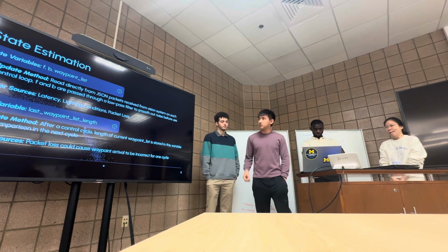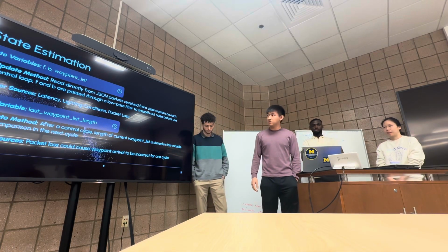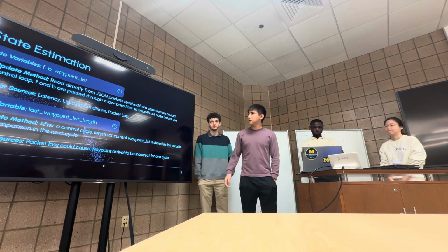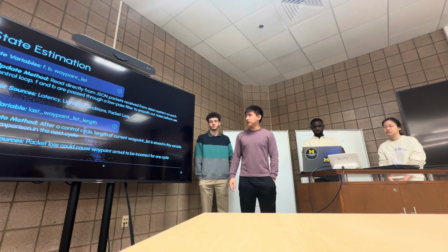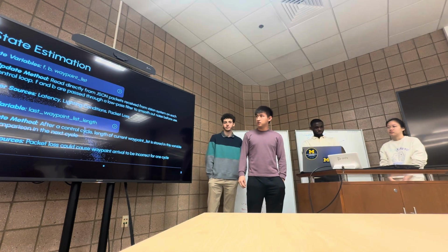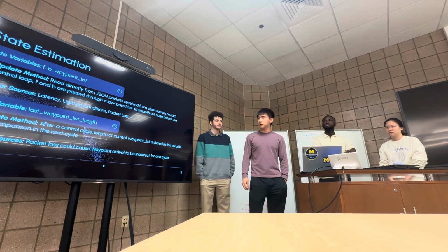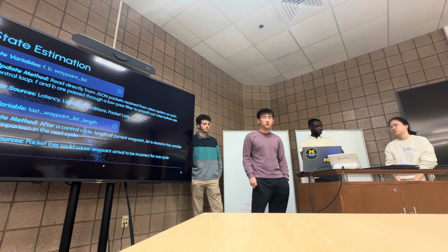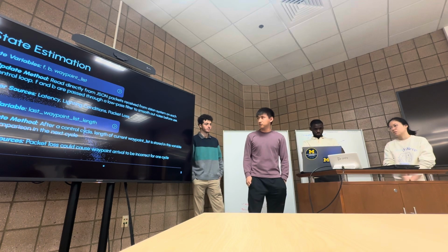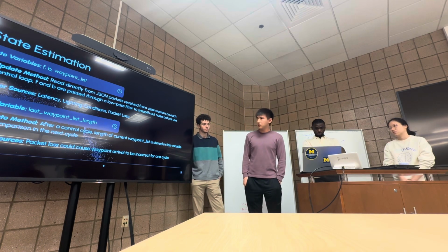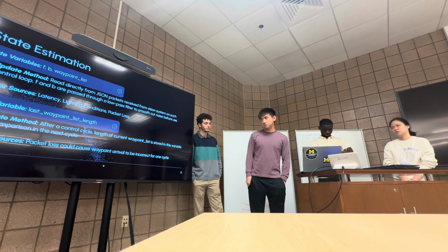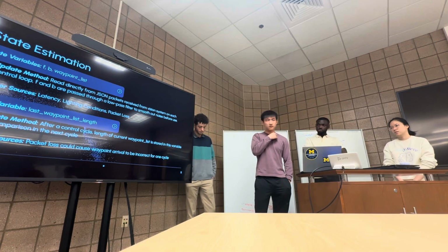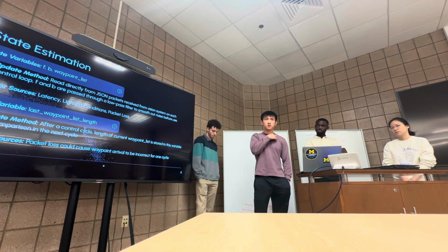For state estimation, we'll get JSON packets, which we'll read, and this will give us the F, B, and then the waypoint list. We'll pass F and B through a low-pass filter to smooth out noise before use. Some errors that could come from this are latency issues, the lighting conditions from the camera might not make the tags readable, and then some packet loss issues. We'll also have a last waypoint list, which will just have the waypoint list from the previous cycle.